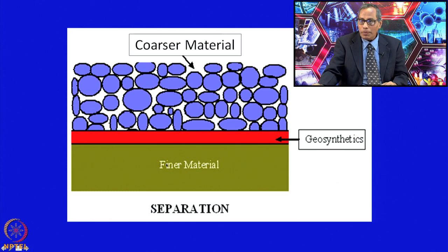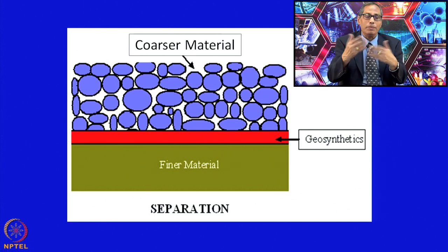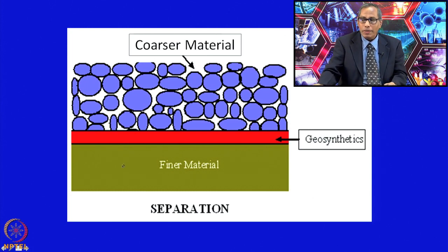On the other hand, if we think of the finer material or clay material, it is good and also bad. When we say the clay material is good, it is because you can use it for the landfill as a compacted clay liner, where it acts as an impermeable material. But it is very difficult to construct any kind of structure when it is very soft clay. So that is bad. Each and every material has a good and also a bad.